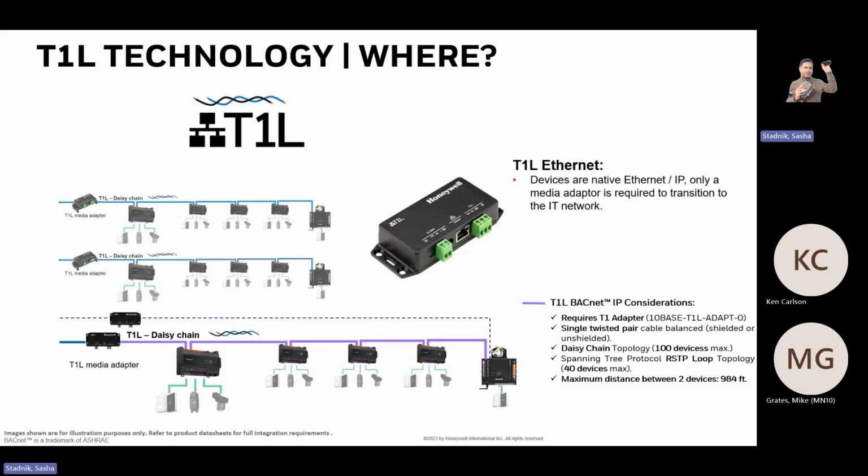Now, people are using this for many things. It's incredible how we as engineers think how to break the rules. And there are people doing like, oh, I have printers on one floor that all of them are IP, but I need to communicate those to a switch or server that is really, really far away. They purchase two of these, and they put the printers in here, and they go twisted pair all the way to that switch. And where that switch is, they put another one, and they convert it back.